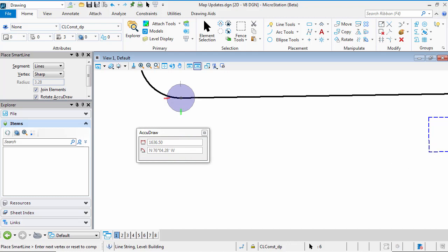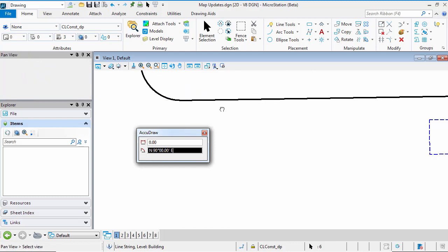Now I'm going to go ahead and do an arc. So I'm just basically tracing over this line again here, as you can see. To do an arc, I want to switch to the arc mode here, and I can use the tilde key, this little squiggle key just to the left of the number 1 on your keyboard, and that'll switch me to arc mode. So now I can go ahead and start to draw arcs,